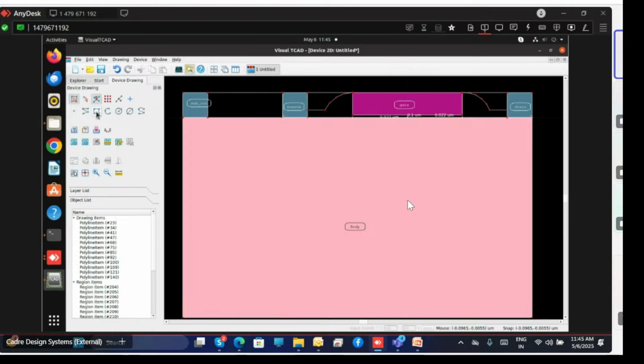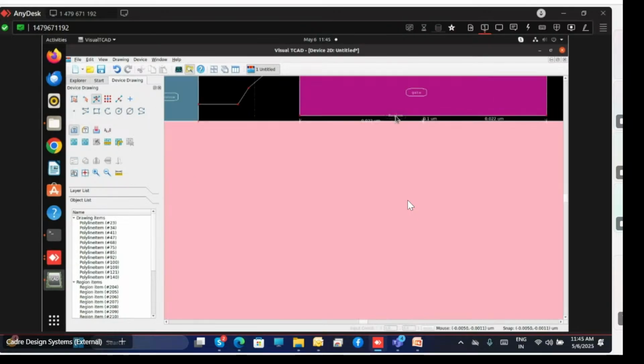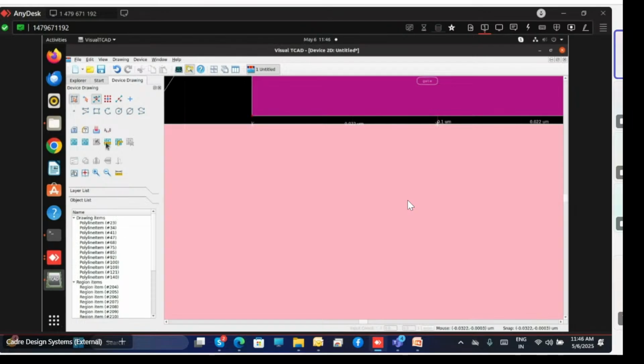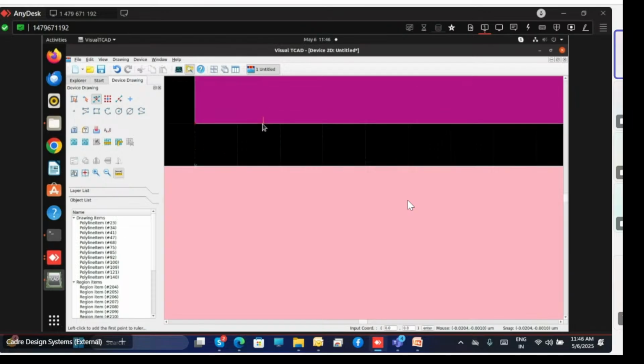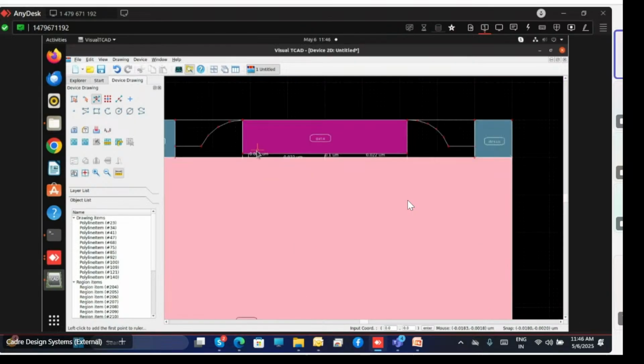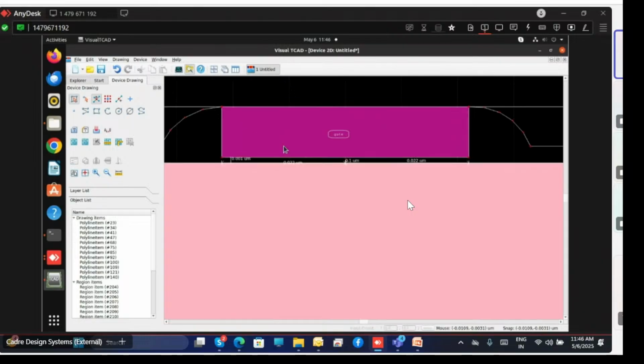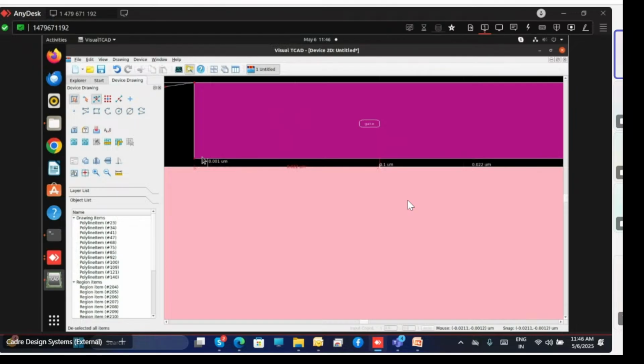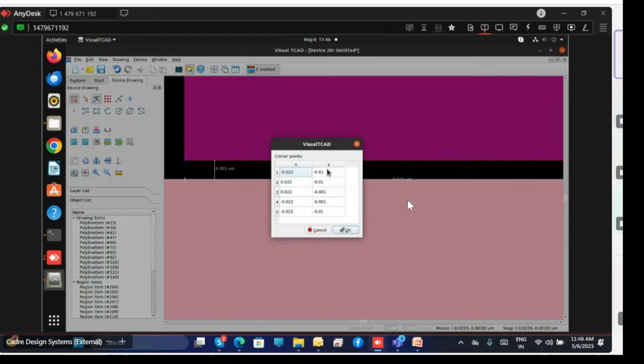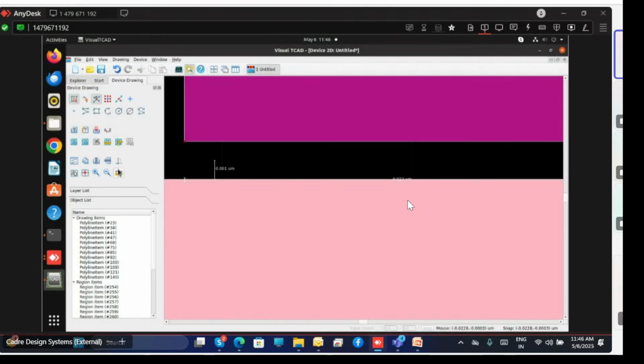Now here we put a gate oxide. Considering the size of gate oxide, currently the gate oxide thickness is 1 nanometer. If you want to increase this thickness, I just resize this box here. So the Y is my 1, so I will consider this as a 2. I will make gate oxide thickness 2 nanometer. So now it is 2 nanometer. I will shift 2 nanometer.